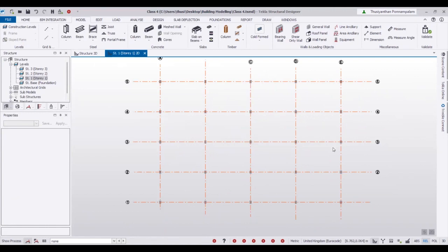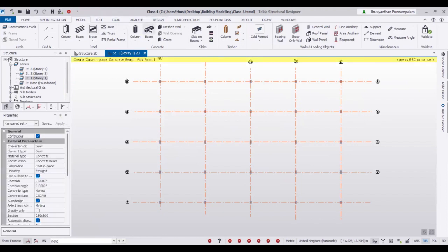That's my system. I choose my beam span as 9 meters. So the rule of thumb I choose is around 1000 by 800, 1000 width and 800 depth. It's a band beam. So these things we can go ahead. I think next week onwards, I'm going to discuss the structural framing. Then I can explain to you how to choose the beam sizes and slab sizes. Now I just take some based on my rule of thumb.